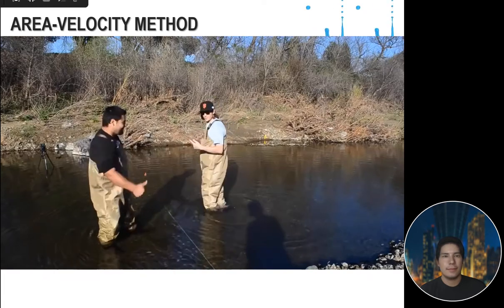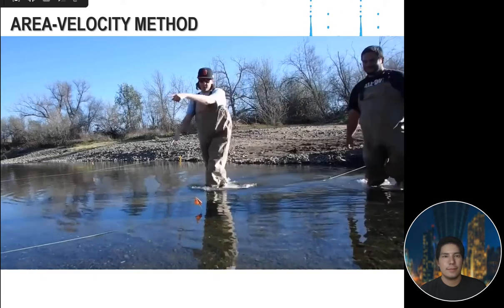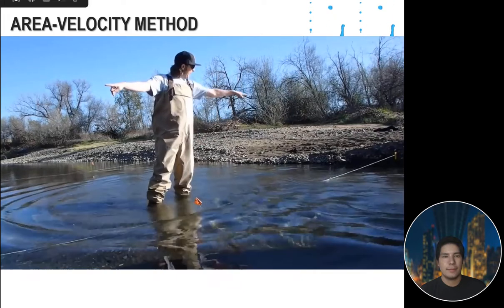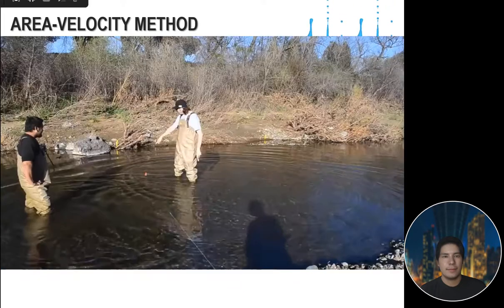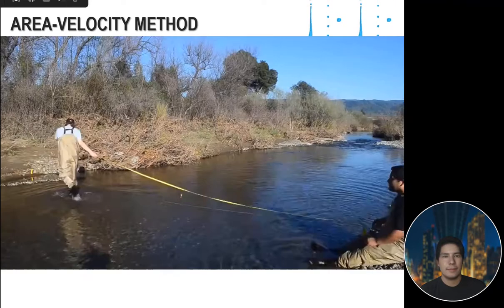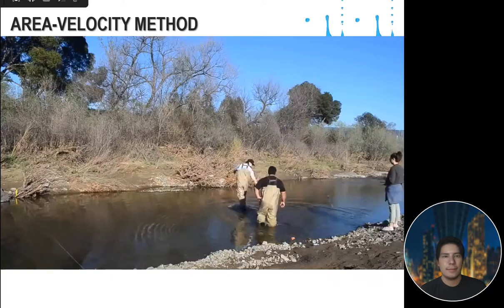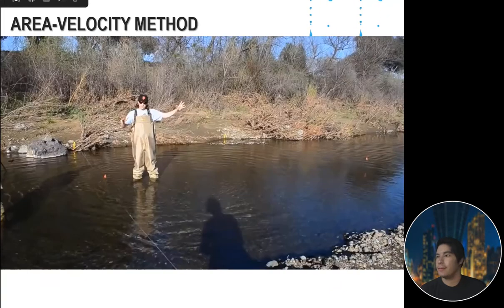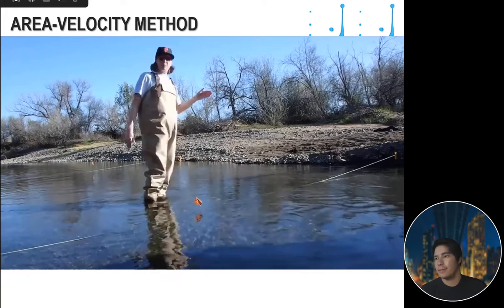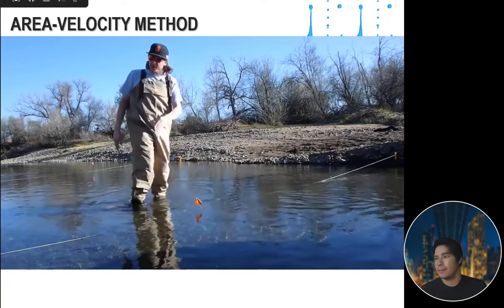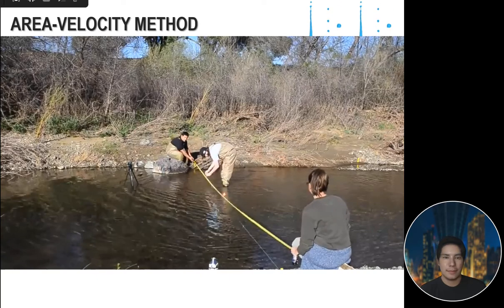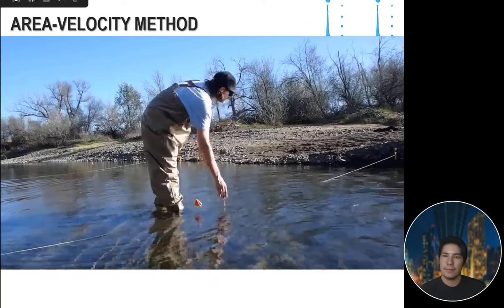The first thing that you want to do is mark an area along the creek. We used camping stakes and a string to mark the beginning line, and then 20 feet away from there, we measured another string, and this is basically going to be our racetrack, if you will, where the orange is going to float and we're going to time it. After you've strung the strings, we measured it and then divided that by 4 and marked it into 4 even intervals that are marked right here.